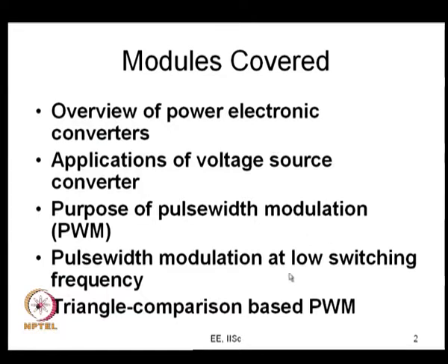The low switching frequency gives us a very good opportunity to learn that, and that is the reason why we went through that. We looked at a single switching angle. With one switching angle we could control the fundamental voltage. With two switching angles we learned how exactly to handle the fundamental, how to maintain the fundamental voltage and also handle the harmonic voltages.